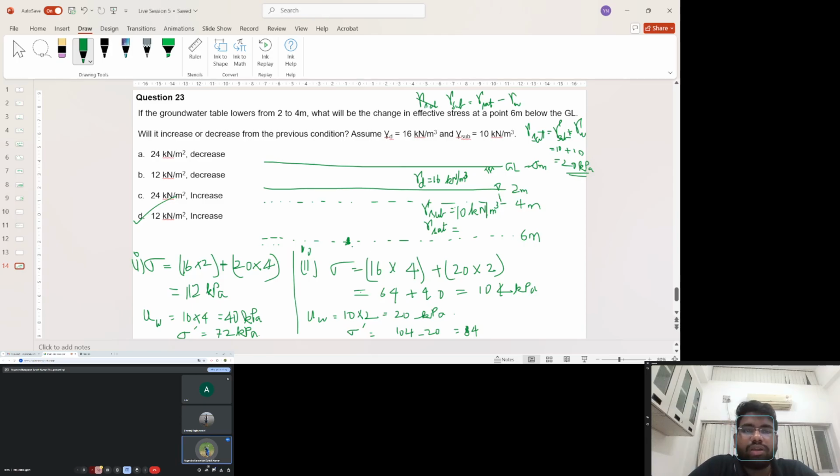All right. So this point, it has several interpretations. Now the effective stress which we are calculating is the stress that is acting on the soil at that point, right? Now if you consider a real life scenario where you are drawing a well, drawing water, or there is a sudden drawdown of water level, that is the most critical condition which we consider for analysis or design.